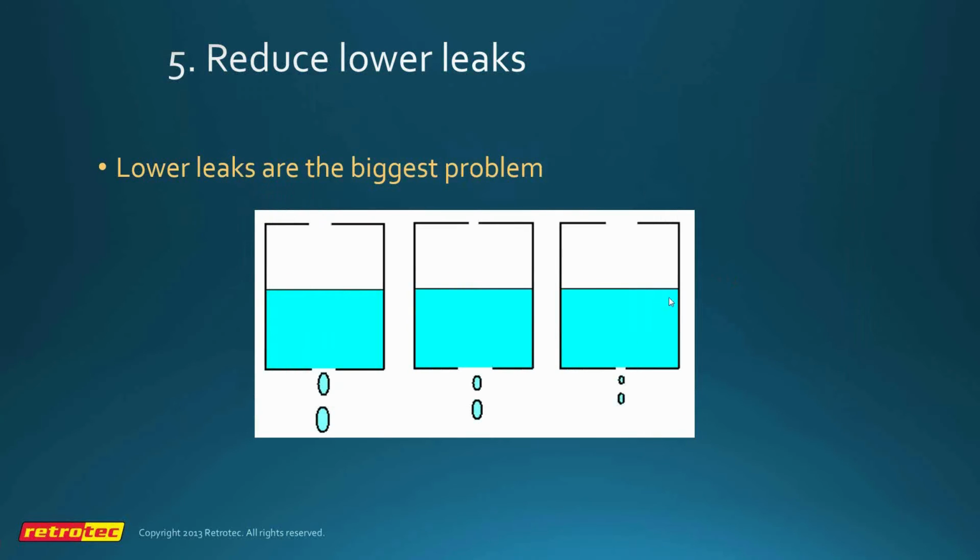So here we show a little graphic that shows how the leakage rate of this heavier than air agent is actually controlled by the size of the hole in the bottom. It makes a little bit of a difference, the size of the hole in the top, but not much. But it's really the size of the hole in the bottom that determines it. If we cut the size of the hole in the bottom of the enclosure in half, we roughly double our retention time, or hold time.